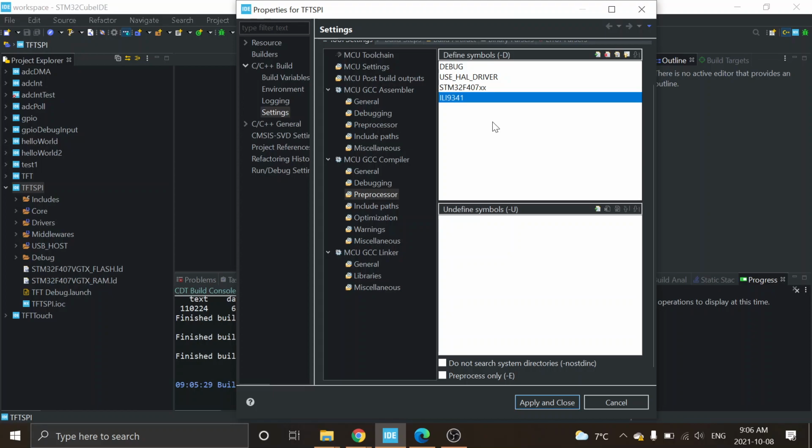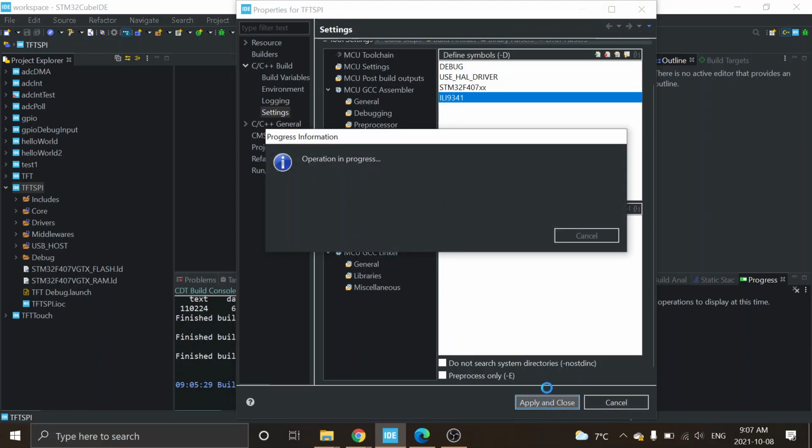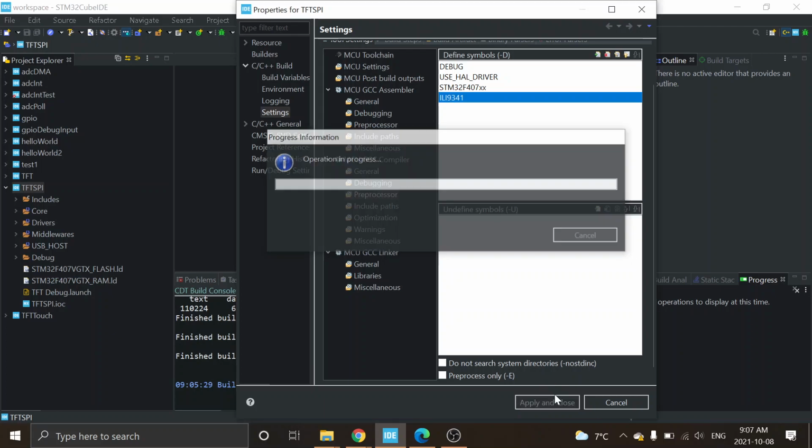You can put conditional compile information in your code to say, if I have this situation, do something. It already does things like, if you're in debug, do a certain thing. You can say, if I have a TFT, so you could just put in a word TFT and go, if TFT is defined, then do the things with the TFT, otherwise go out of serial port or something like that. Conditional compiles. So I've got some preprocessor directives. You have an ILI 9341.